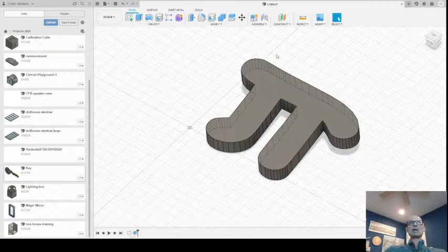That is a real quick way to show how you would import a DXF or other type of CAD file. Insert in the toolbar, insert DXF, or you could also insert SVG. And that allows you to quickly get up and running from a 2D sketch and take that into the third dimension if you so desire. That or apply 2D CNC tool paths to it.